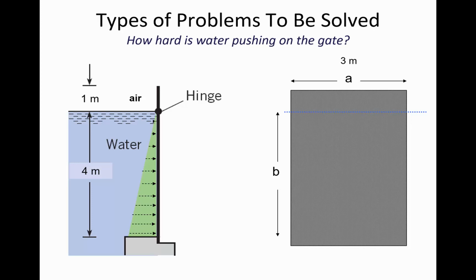And the reason why we're doing this is oftentimes it's convenient, instead of considering the pressure distribution, for us to understand what's the equivalent force. What's the magnitude of the equivalent force and what's its location. And so here in brown, you can see that I've indicated that there's some equivalent hydrostatic force acting on the gate. So that's what F stands for.